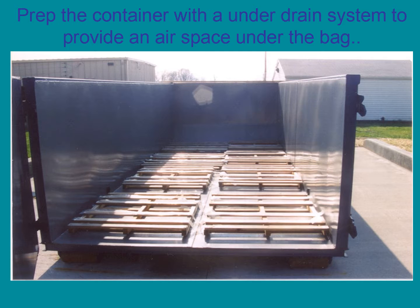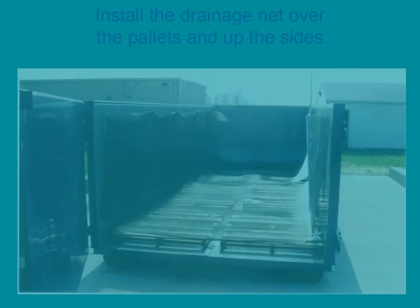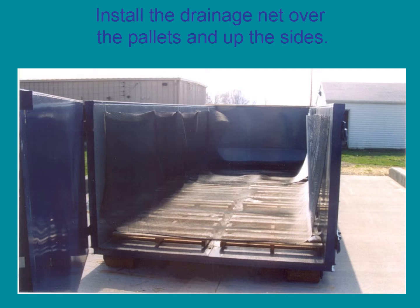First, prep the container with some kind of airspace under the bag. It can be as simple as wooden pallets under the bag, or corrugated 4-inch slotted drain pipe can be used to provide a space for the effluent to flow rapidly out of the container. Drainage netting is installed over the airspace and up the sidewalls of the container.